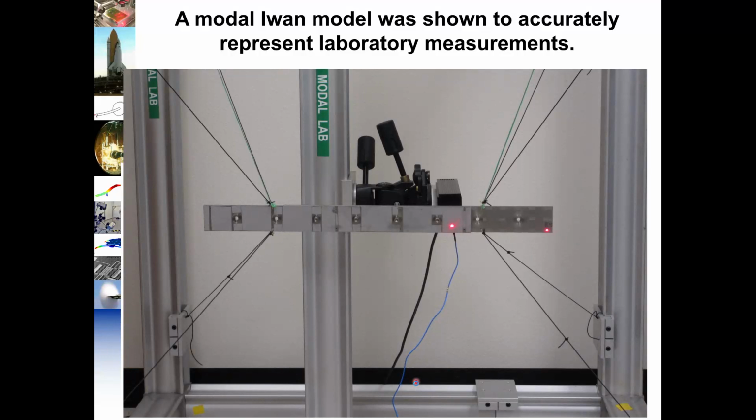So here's one example that we did in our group, a test on 2 beams that overlap in this region here. And so there's 4 bolts holding them together there. So we suspended them with bungees and used a laser vibrometer to do the test.